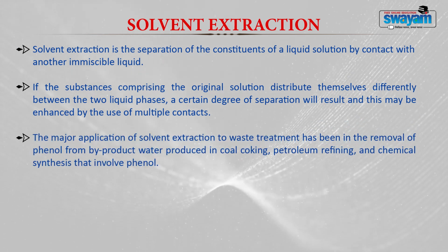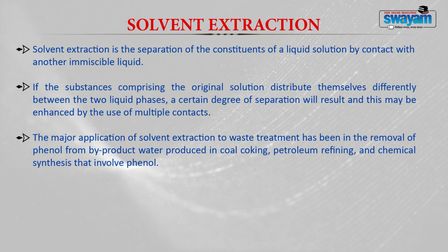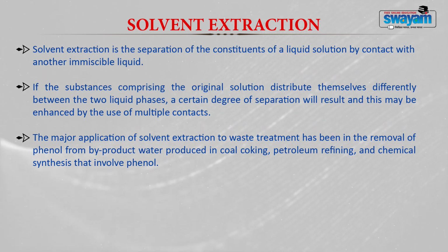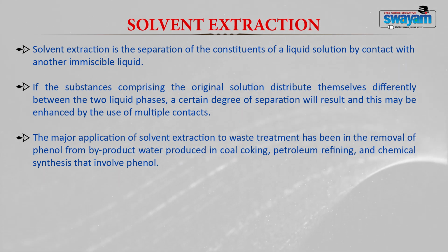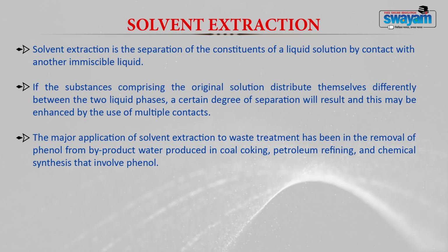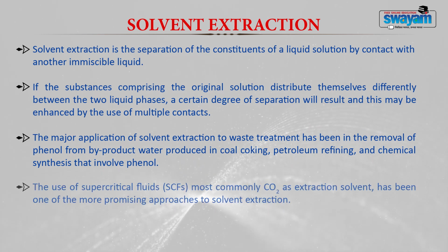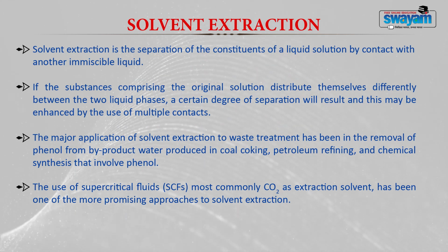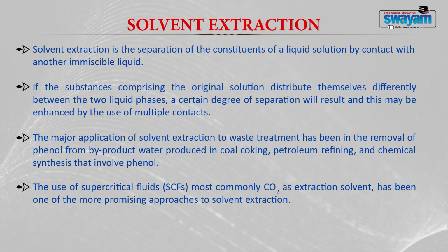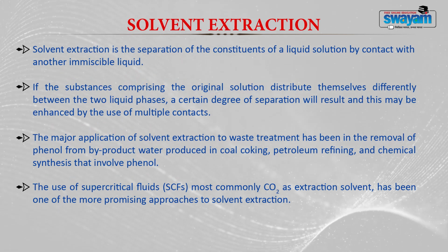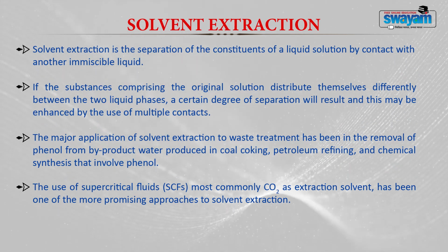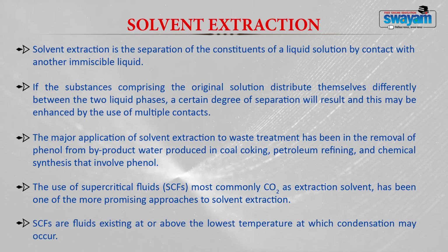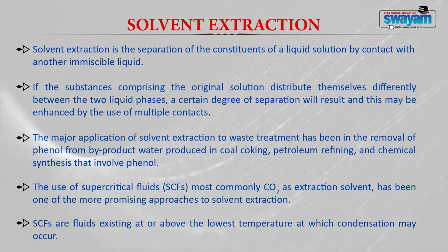Now, the major application of solvent extraction to waste treatment is the removal of phenol from byproduct wastewater produced from coal, coking, petrol refining and chemical synthesis that generally involves phenol. They also use supercritical fluids, for example carbon dioxide, as an extraction solvent. They are also being used and it is considered as one of the promising approaches in solvent extraction. Fluids existing at or above the lowest temperature at which condensation may occur can be generally used for this